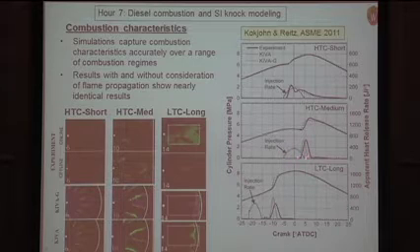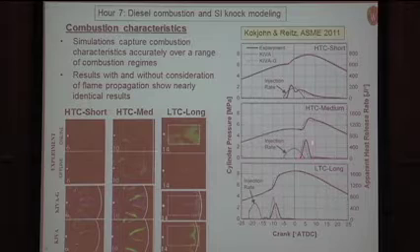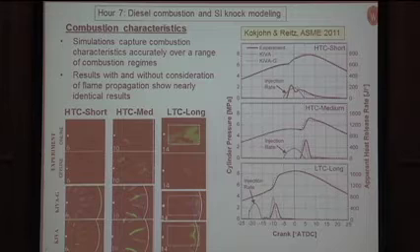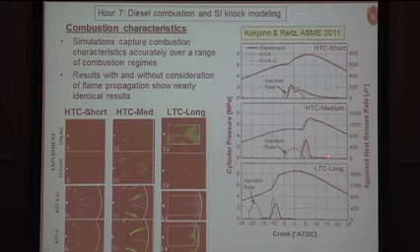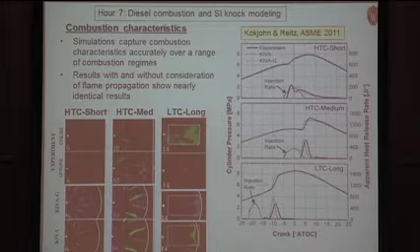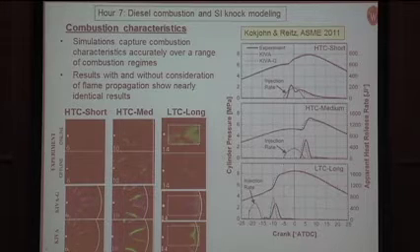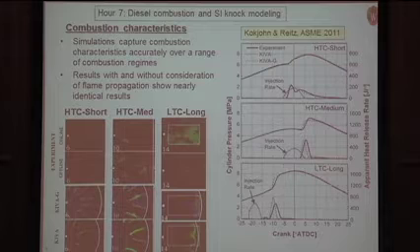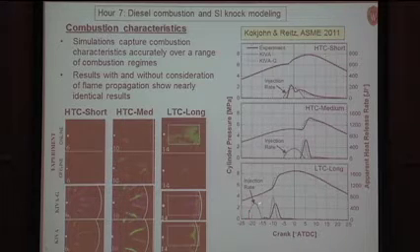Here's the end of the injection. Combustion is delayed relative to what we saw here. And in fact, we see more of just a premixed burn because the fuel has had a lot of time, or more time, to premix, but there is still evidence of some diffusion burn. And then finally, for the long ignition delay case, or like the PCCI case, we start the injection about 20 degrees before top dead center.